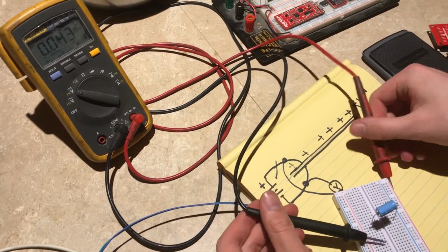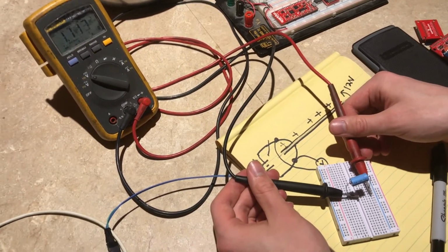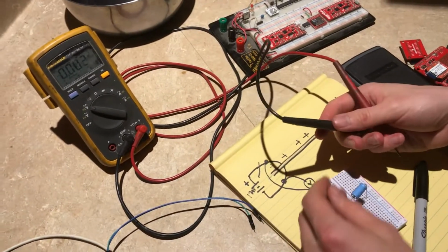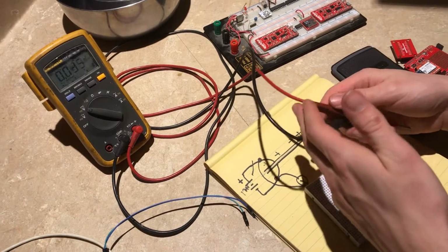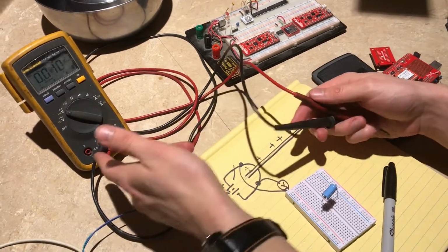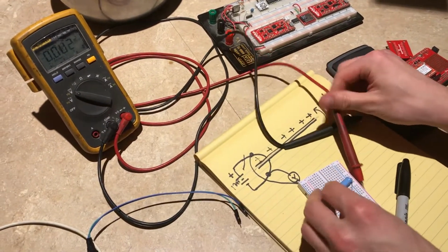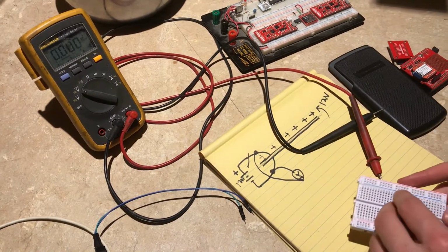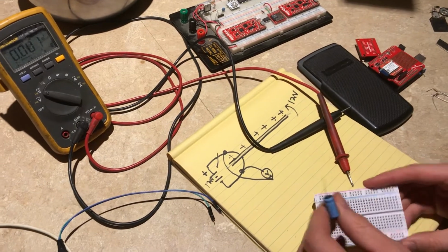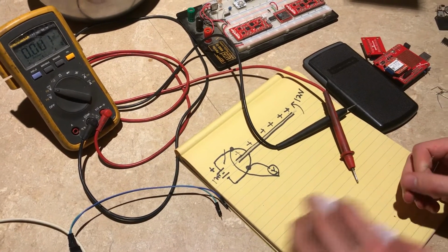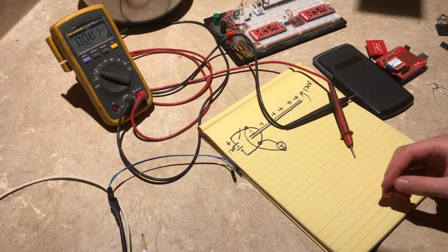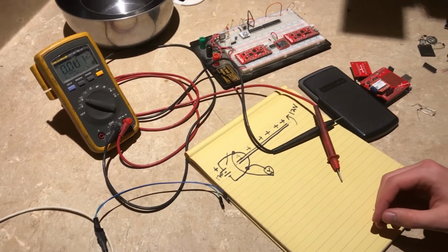But you can see this thing is storing voltage. Why is the number dropping? Well, some of the stored charge is leaking out as current through the voltmeter just a little bit, but it's enough that as you wait, the voltage drops. But that goes to demonstrate that electric charge can be stored in a capacitor in that manner.